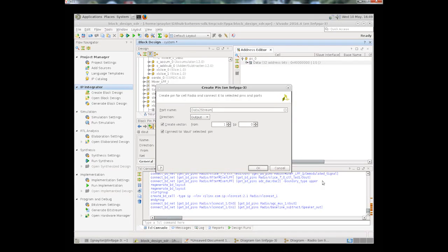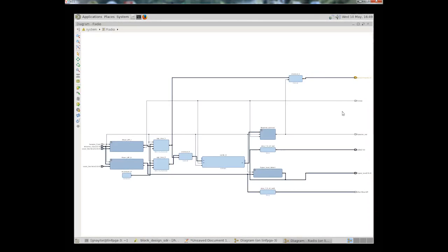That's what we're going to stream into the ARM processor. Now you remember that this data is being updated at 32 kHz, so the other signal we need as well is this strobe signal, which is a 32 kHz timing signal.